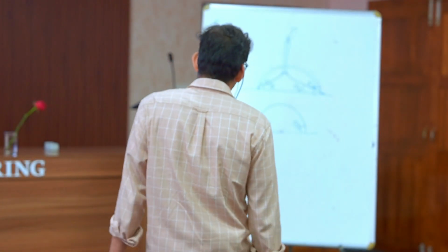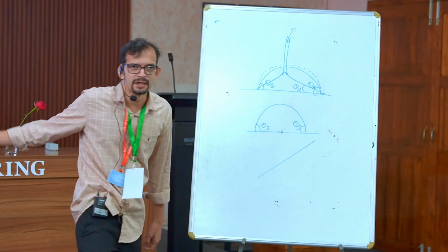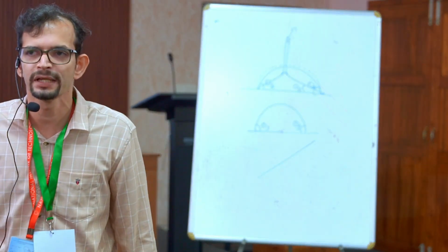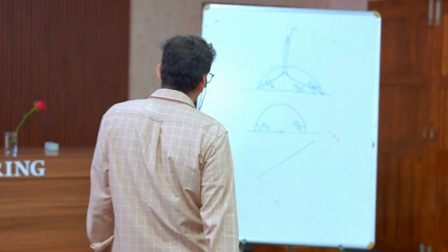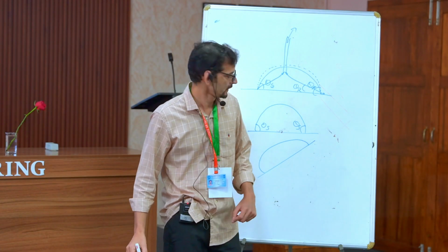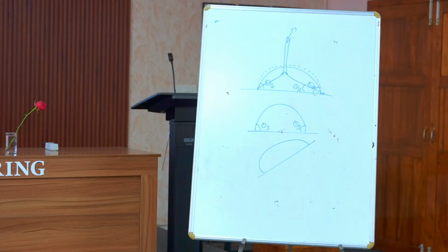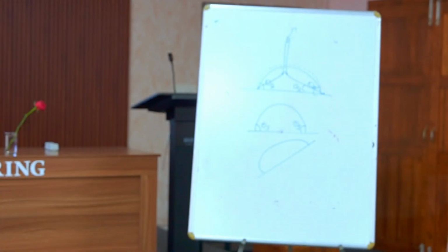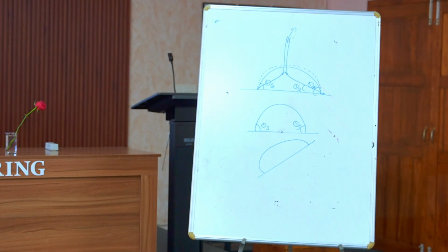Now I am tilting. In tilting, what happens? When I tilt, the gravity is there, right? It is not like a nanoliter droplet, right? It's like some microliter droplet I am putting, right? And then what will happen? It will acquire a shape like this before it starts to move. Here again, I am taking a caution. If both are the same, it will start immediately when I try to tilt, right? But in reality, it takes time or takes an angle to do that, right? You can see a droplet in an anisotropic state.